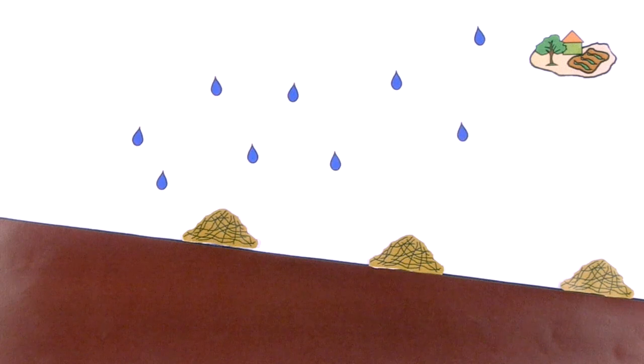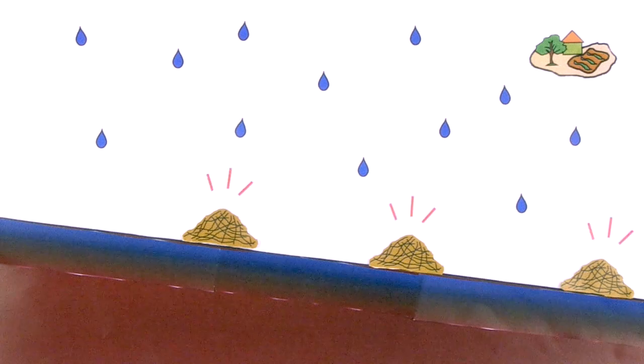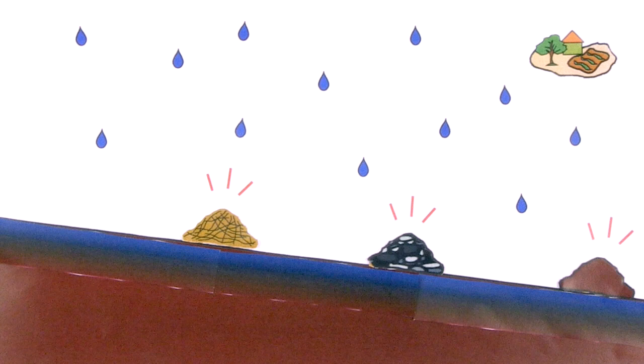Contour or key line barriers are constructed perpendicular to the slope. Their function is to intercept rainfall, encourage infiltration, and to reduce soil erosion. Barriers are built from vegetative material in trash lines, stones, or soil. Other cross-slope systems are swales and living terraces.